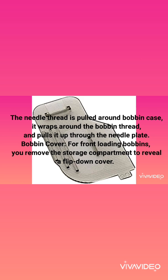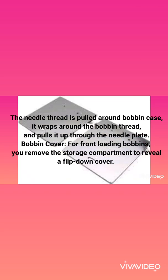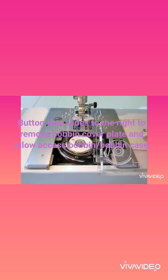Bobbin cover. As the needle thread is pulled around the bobbin case, it wraps around the bobbin thread and pulls it up through the needle plate. Bobbin cover for front-loading bobbins: you remove the storage compartment to reveal a flip-down cover. Bobbin cover release button. Button that slides to the right to remove the bobbin cover plate and allow access to the bobbin or bobbin case.